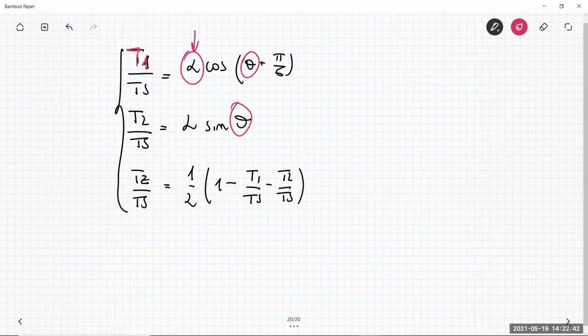These formulas are in a form that can represent any specific code stored into the memory of microcontrollers, microprocessors, FPGAs, etc., in order to make the control fully digital, for example. And so you can store this expression, and the position theta can be acquired from your frequency, etc. And then it is a computation that does not require any analog comparison between a triangular waveform and a sine wave, for example.